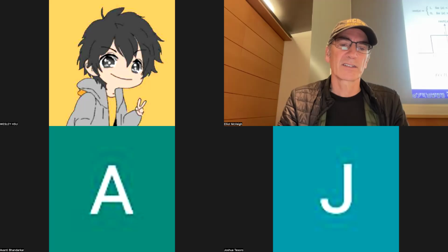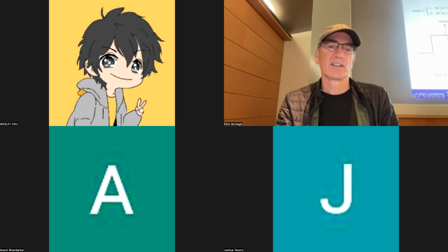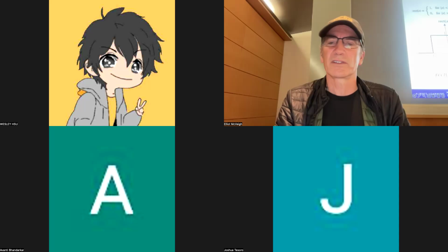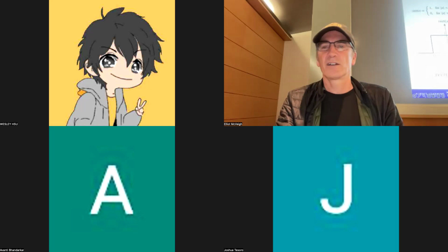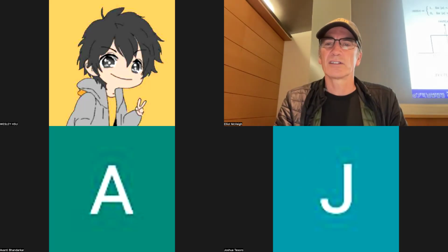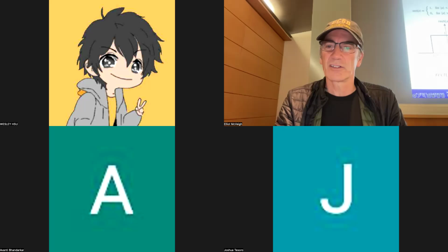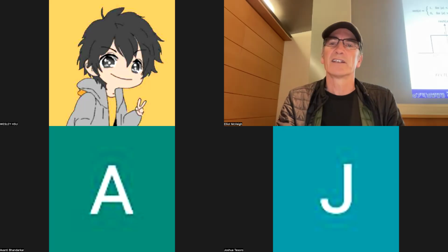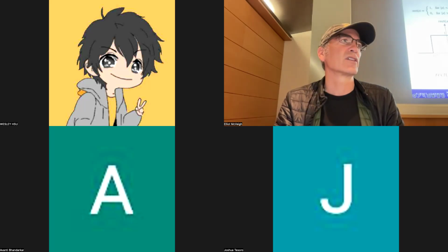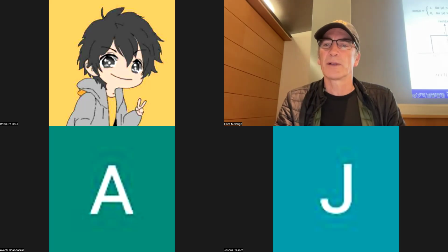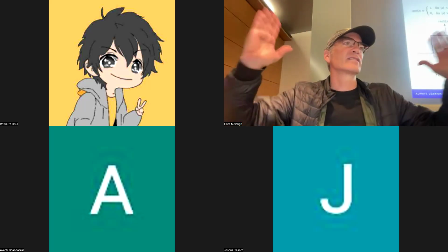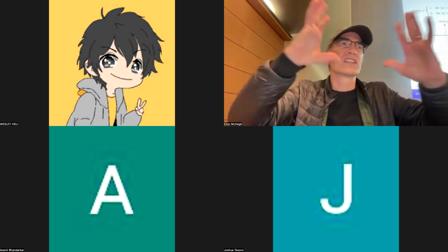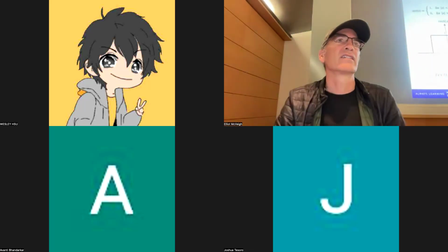I think in the book they use a different notation, but most of the time we'll just say rect. And then this is another function of tremendous value, called the sinc function. You can see it looks like one of those sombrero things. It has a peak of unity, comes down, has its first zero here, and then a negative peak, a positive peak, a negative peak. So it's kind of like a wavelet. It has position in space, and it's got this peak there.